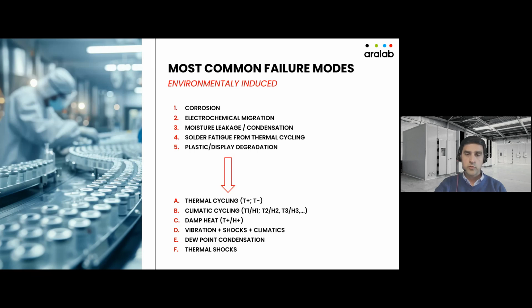The automotive industry, for example, the standard is -40. In our aeronautical industry, we can take samples down to -75. So all of this helps us determine whether or not that equipment is sturdy enough. Also, a very common example that I think allows you to understand what climatic cycling is.